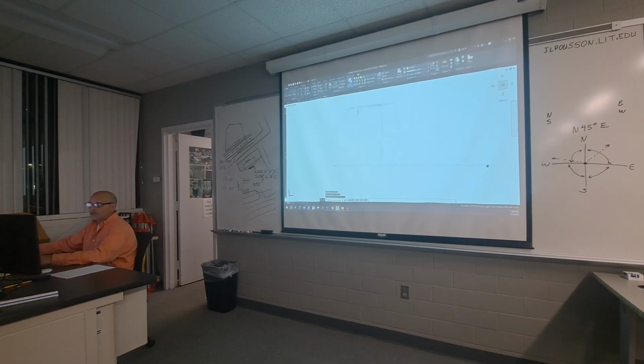2 foot, yeah, that'll work. All right, so my first side, I picked my first point. Like I said, I'm in my polyline command. Our relative polar coordinates formula: at, the distance, is less than, the angle. So I type in the at symbol. My distance for this side is